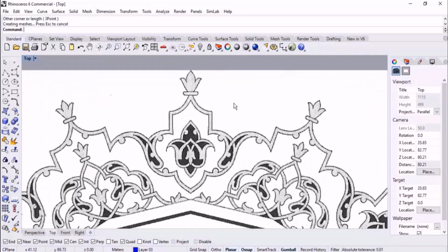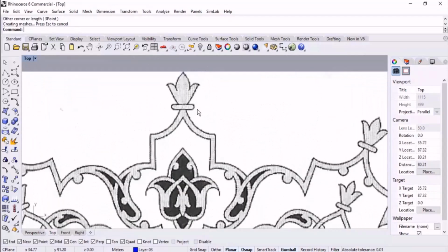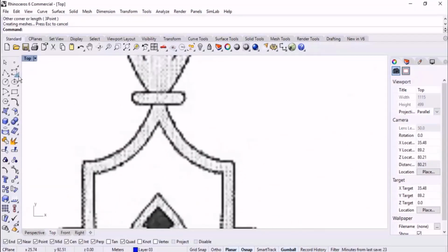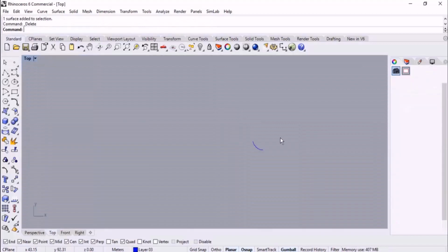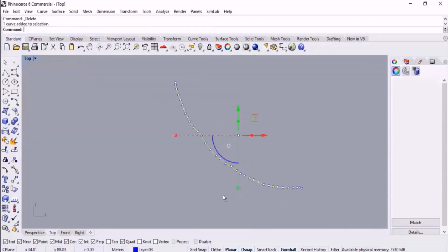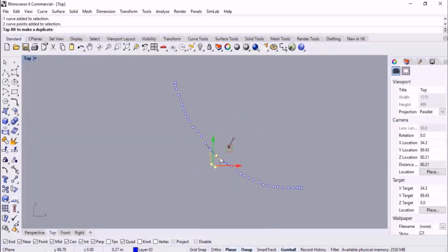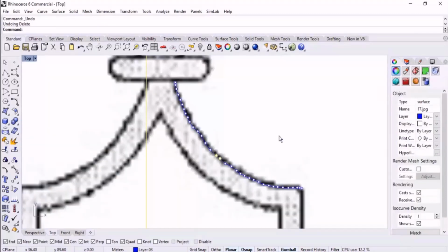So I open the top view, then I start sketching. Here there are some points. First of all, while you're sketching the pattern, we were supposed to sketch it by interpolate points, curve interpolate points. As I told you before, you should have fewer control points. This type of work, or stressy, as I told you, is not accepted. This is not satisfying and accepted. Let me show you the curve. As you can see, it is not smooth and it is not editable, so it is not standard.